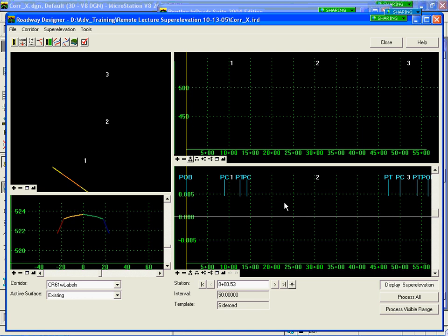And they are automatically assigned to points on a template, and when coupled with a reference point or pivot point, as in previous versions, it achieves superelevation relative to the pivot point. Also, it's good to note that they override normal point constraints that are stored in the template.